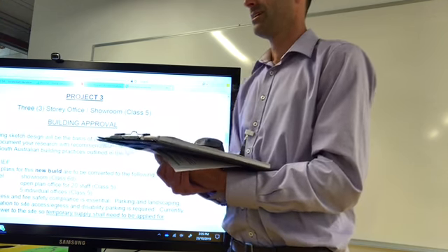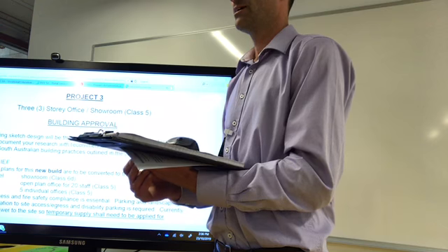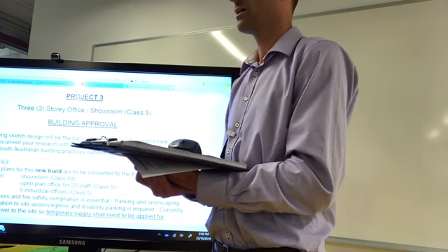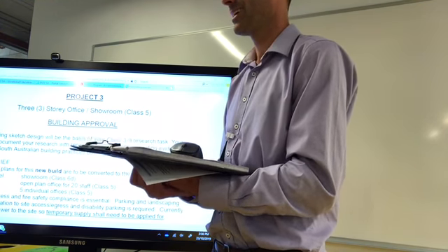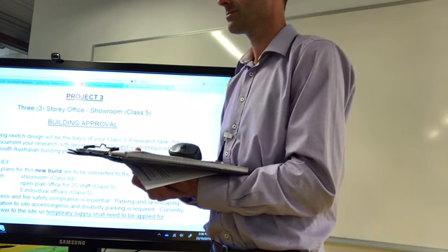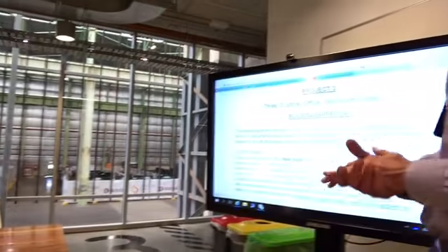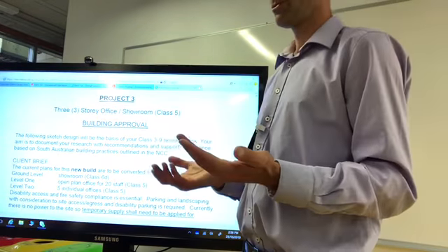Yeah. It really depends on what form you wish to explore. I tend to think the box gutter detail is probably something you're more inclined to use, so explore that one. What's it like to install though compared to the other one? Because the box gutter detail is harder to install and easier to screw up. So what's the other one like? Yeah, so the other one is essentially much easier to draw, much easier to install.